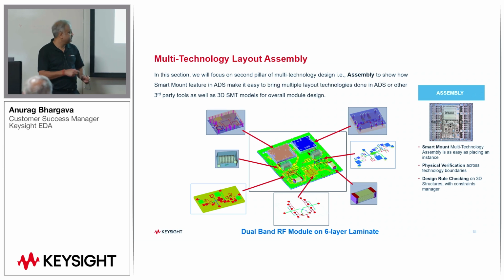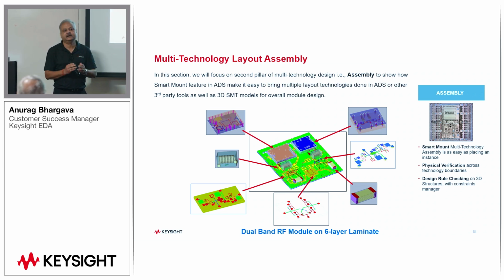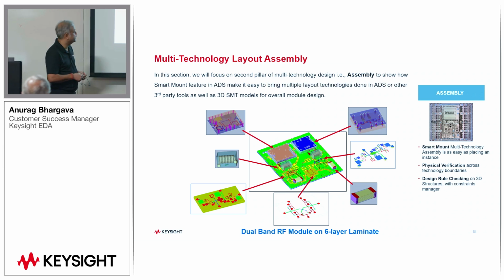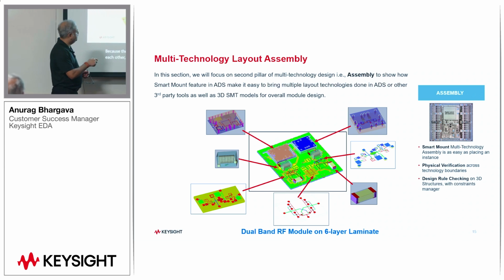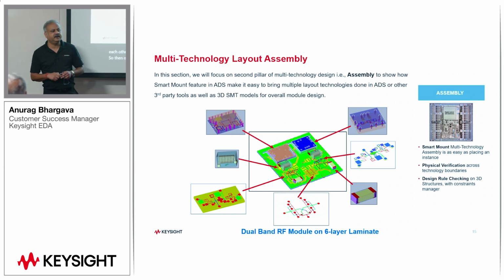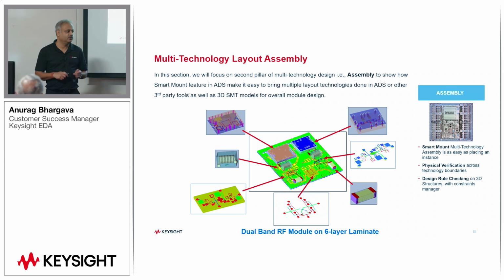A 3D model of an SMT might be coupling with your IC because there will always be a fringing field, and if they are placed very close to each other, you may have all sorts of couplings here, right? So then our platform is also ready to get these vendor 3D models and have them included.